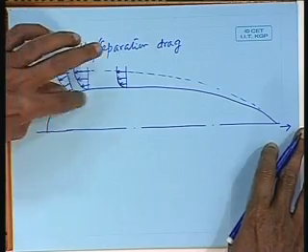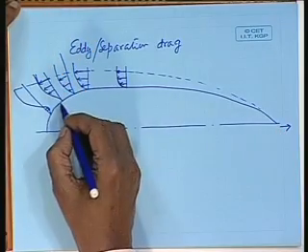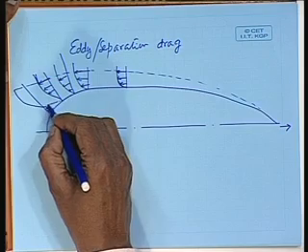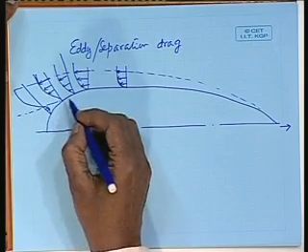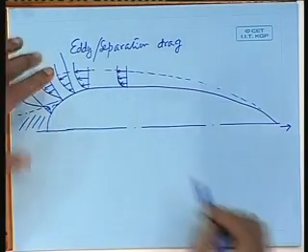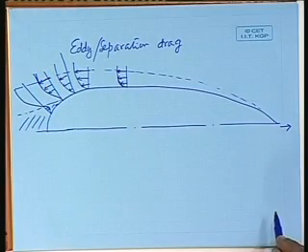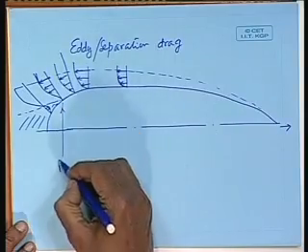This is happening because of the large slope of the body here, large curvature. So, what happens? As if a layer is being formed here, with this being the 0 velocity point, where this flow is separated flow inside the boundary layer. Clear? This is the point of separation.